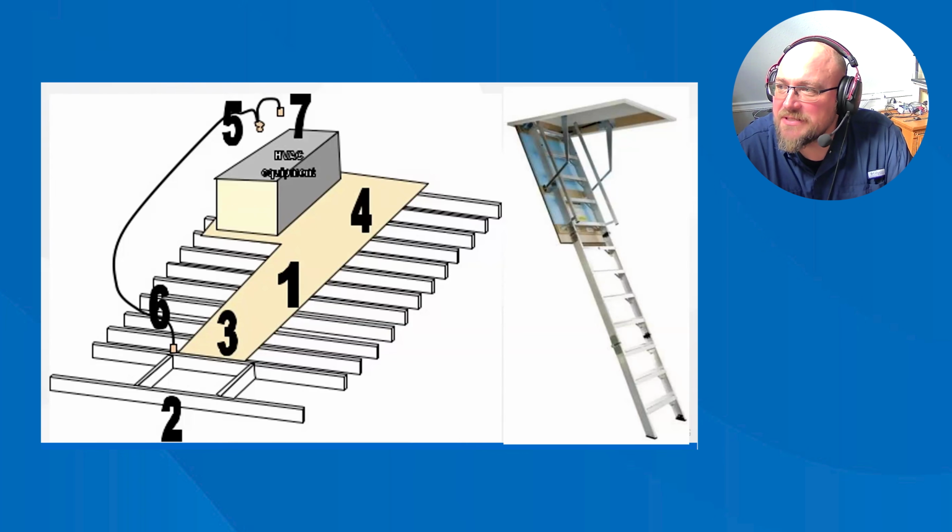Lack of insulation. Hatches in many houses, especially older ones, are not likely to be weather stripped or insulated. An uninsulated attic hatch allows air from the attic to flow freely into the home, which may cause the heating or cooling system to run overtime. An attic hatch cover box can be installed to increase energy savings.